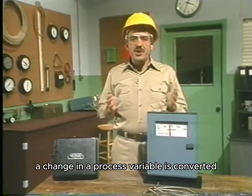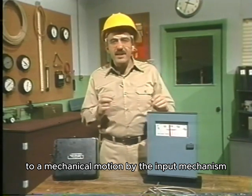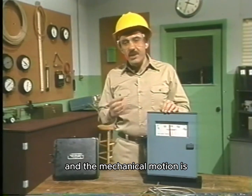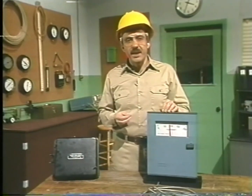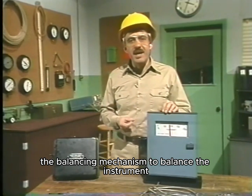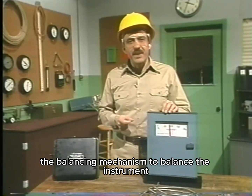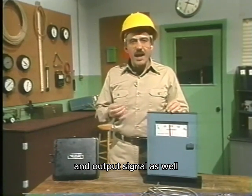What happens is a change in a process variable is converted to a mechanical motion by the input mechanism, and the mechanical motion is converted to a back pressure by the error detector. Later we'll see how this back pressure is sometimes used by the balancing mechanism to balance the instrument, and how other times the back pressure is used to generate an output signal as well.